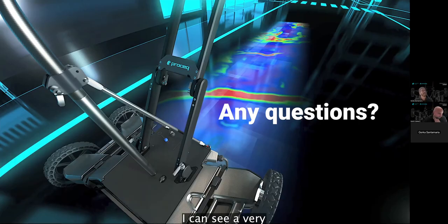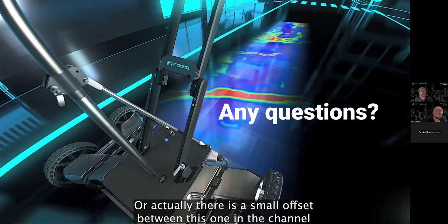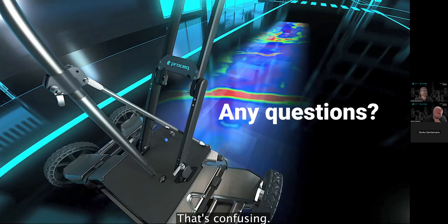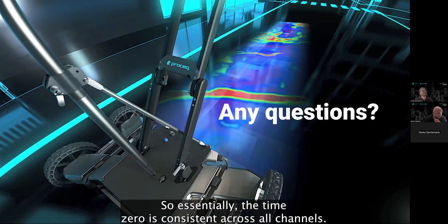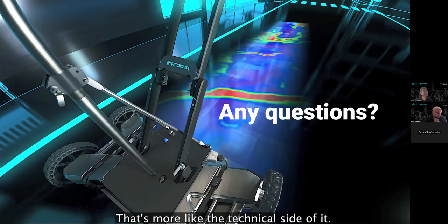I can see a very clearly defined reflection in this channel, but not in the next one. Or actually, there's a small offset between channel 1 and channel 2, and actually it should be the same. That's confusing. Because step frequency works in the frequency domain, it doesn't get affected by these problems. So essentially, the time zero is consistent across all channels. The gains are also very consistent across all channels. That's more like the technical side of it.